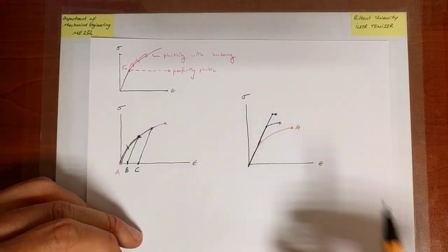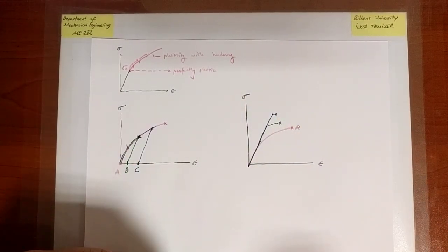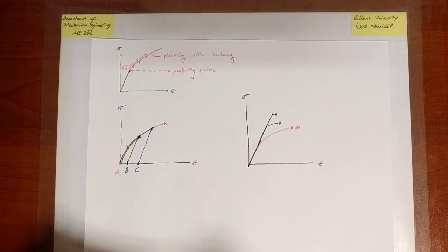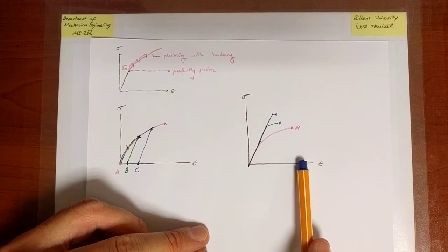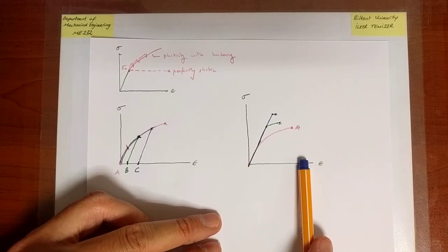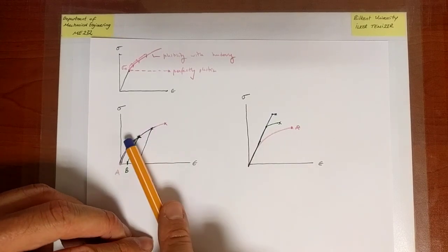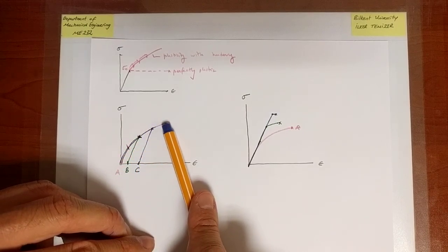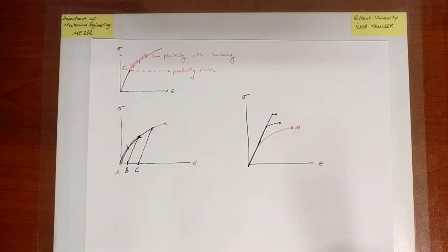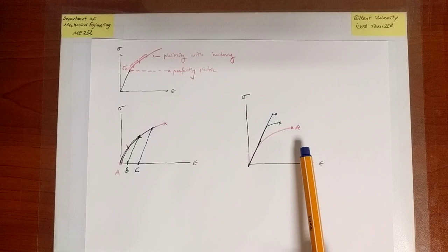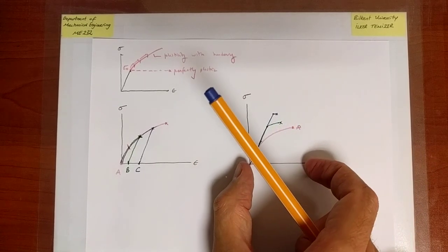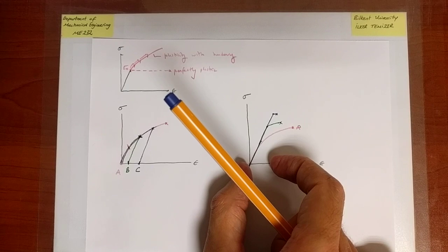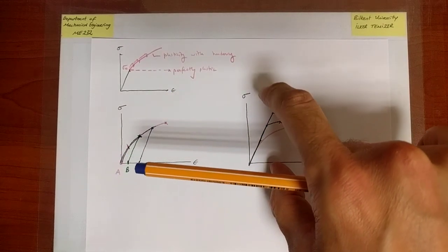Now here I've modified the failure stresses a little bit, but the point that I'm making here is that typically, when you deform a material plastically, it really gets harder to deform, first of all, because the stresses that you have to apply are continuously increasing. But also, two strange things happen. We're not going to directly model this, but two strange things happen that are very important for manufacturing and modeling steps. One, the ductility of the material decreases with deformation, and two, the yield strength will keep increasing.